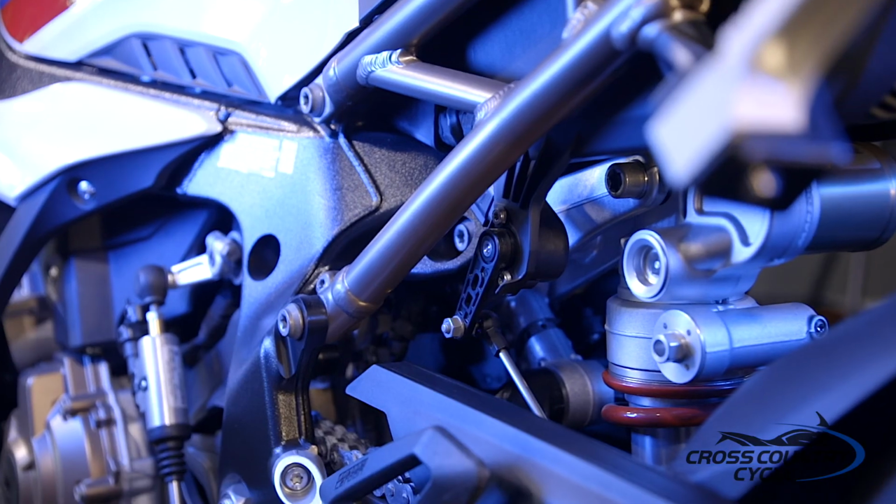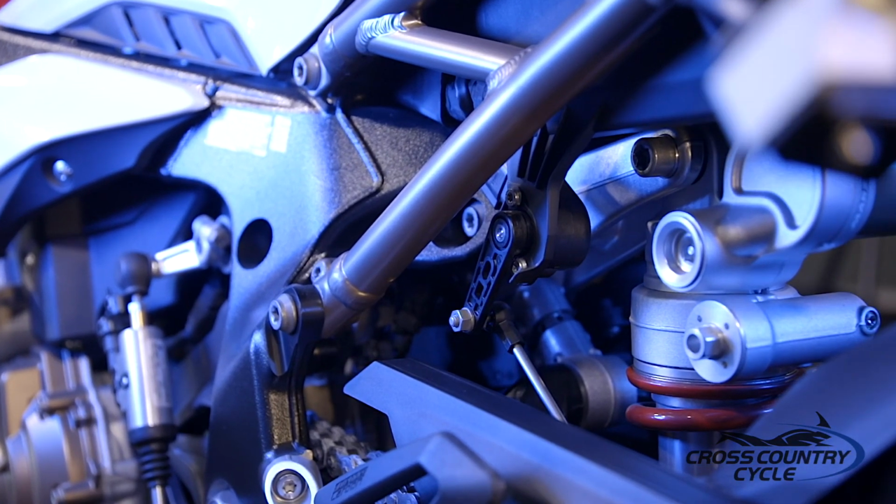So why is this? This is because DDC uses ride height sensors known as potentiometers to identify where the suspension is in the stroke and the velocity it is traveling at during the movement. The rear shock has a ride height sensor as seen here, but the front does not. In order for the front suspension to have separate compression and rebound, you must install a front potentiometer, which is a racing accessory. This accessory can be purchased through Alpha Racing, the official partner of BMW Motorrad Motorsport.